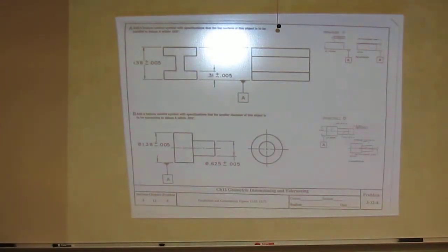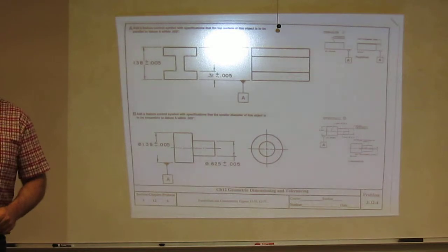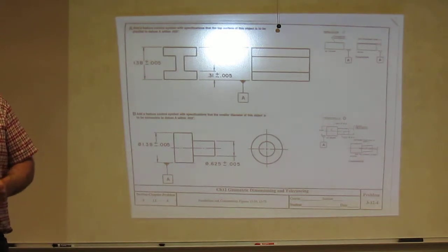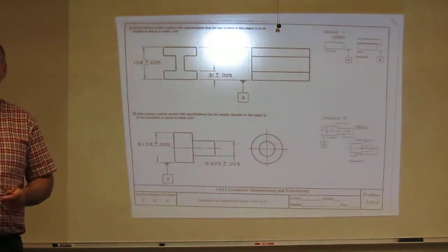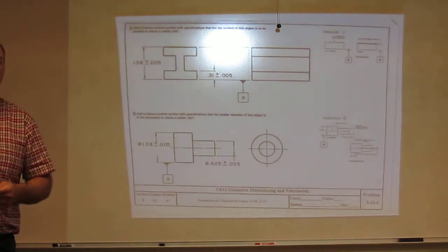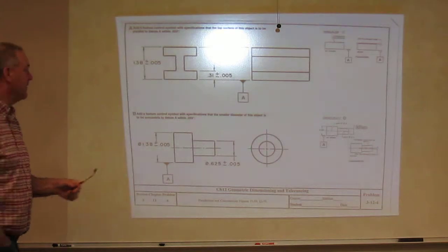So these first two sheets are all about learning how to make this control box where things go. And so you're going to have 4 little repetitious exercises to help you with that. Now remember, your text is an 1/8 inch when you do these. So you want to make sure your box, when you put it in, it's by hand. You're going to do this with a pencil. Make sure your box is 1/4 inch by 1/4 inch minimum, so that your text is not crowded by the border of that GDT box. So you're doing this one.